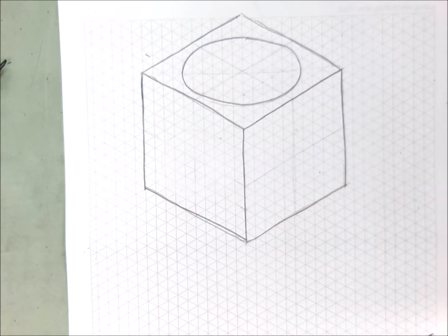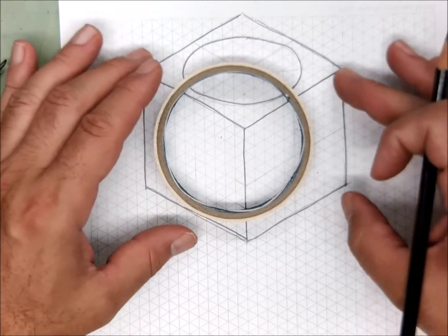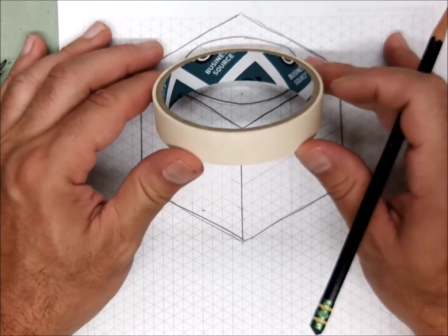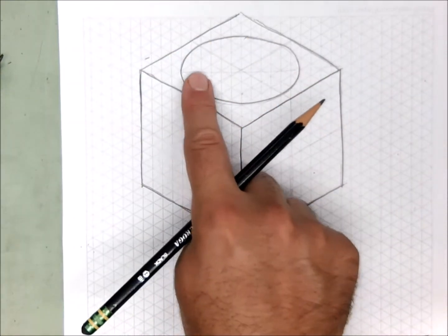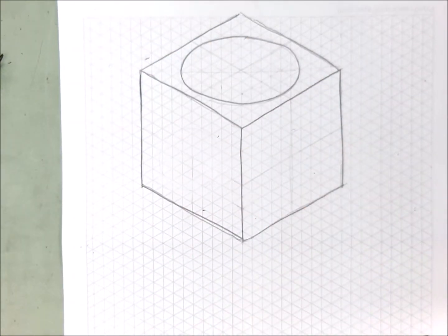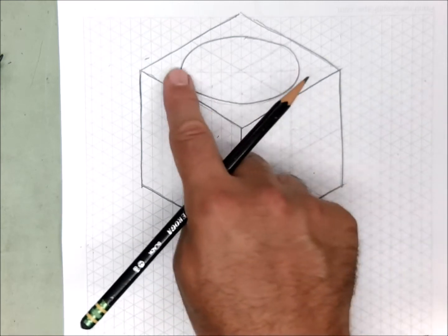Okay? So think about it. Here's a round hole, and we tip it up. Doesn't the long axis go left to right? And here it does, go up left to right. Now, anything drilled in a top surface will have an ellipse that goes long ways left to right.